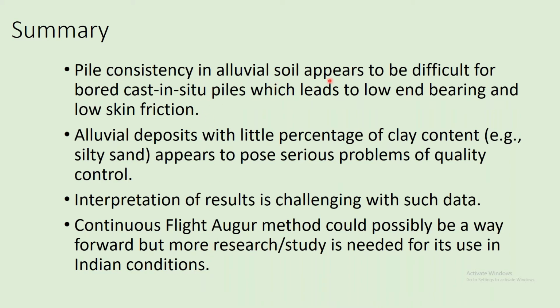Pile consistency in alluvial soil appears to be difficult for bored cast in situ piles, and this leads to low end bearing and low skin friction. Alluvial deposit with a little percentage of clay content appears to pose serious problems of quality control. Interpretation is also changing from such data, and CFA looks like a possible way forward, but a little more research or study is needed for its use in Indian conditions.